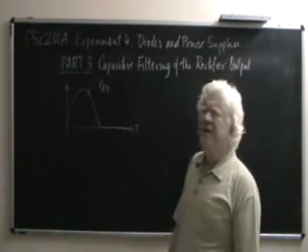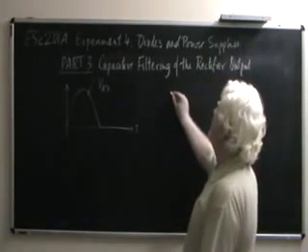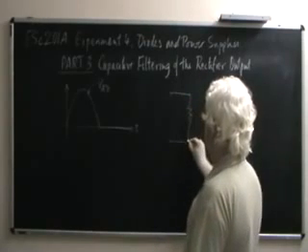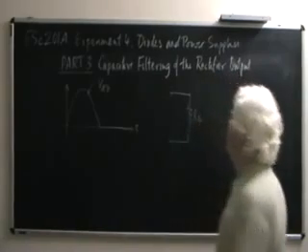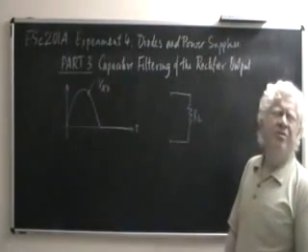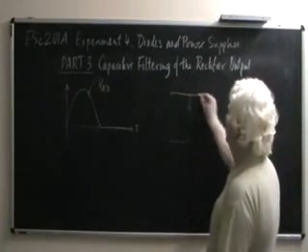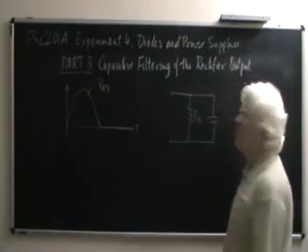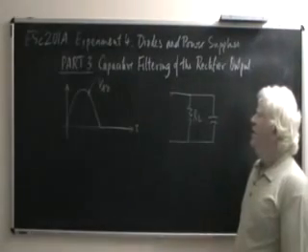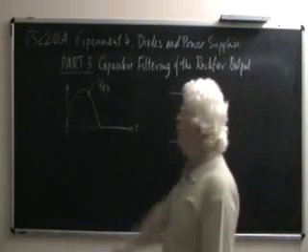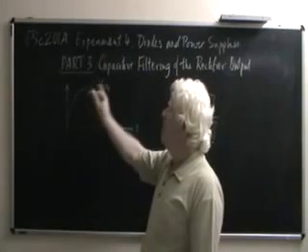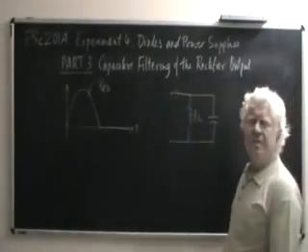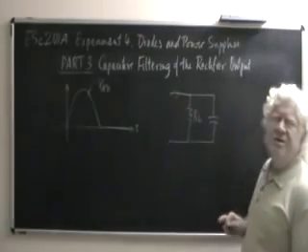So now what we propose to do is this. Let this be any rectifier, half wave or full wave, across which we have the load resistance RL. We propose to put a capacitor across the resistor. What does this capacitor do? When a non-zero voltage is applied by the rectifier to this part of the circuit, this capacitor will charge